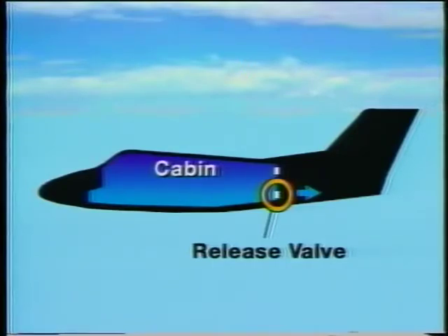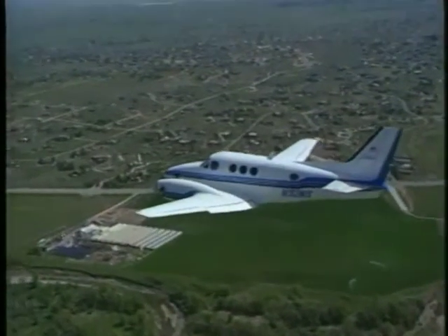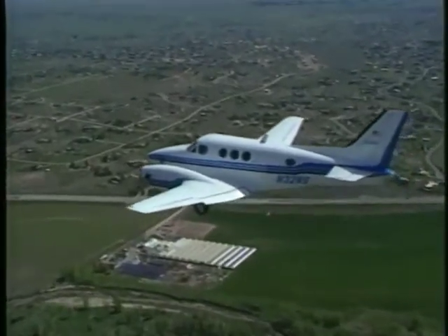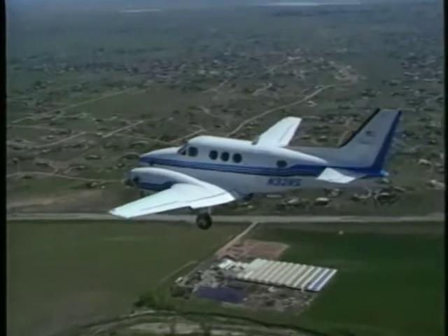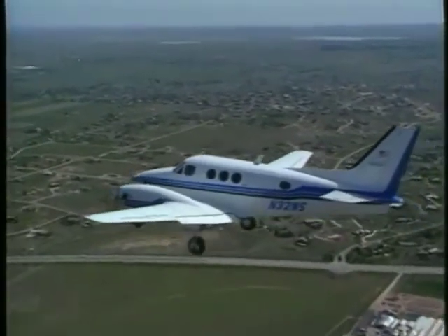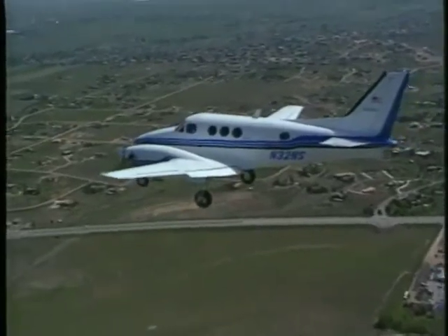This valve can also be connected to the landing gear safety switch so that anytime the gear is down and the switch is open, the cabin depressurizes. It may also be manually opened in case a turbocharger fails and contaminated air enters the cabin.